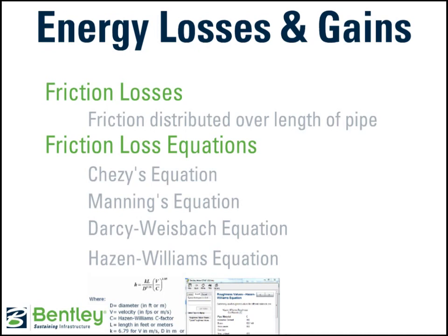The Manning's equation is used to model open channel flow. It's most frequently used for sewer system calculations, so we won't examine it in depth. The Darcy-Weisbach equation is not commonly used in the US, but it is frequently used internationally. For the work of EWB chapters, the engineering standards may be driven by local standards and policy. Luckily for you, in WaterGEMS it is very easy to try these different friction models.